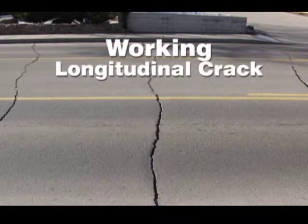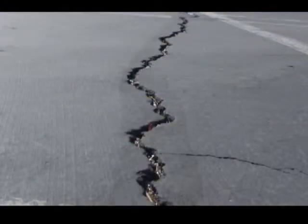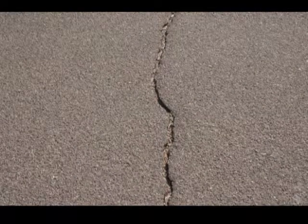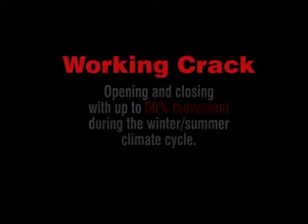The second type of crack is the working crack. The longitudinal crack is the most common type of moving crack, and we will focus on the proper type of crack repair for these types of cracks in this presentation. A working crack will move, meaning it will expand and contract, opening and closing with up to 50% movement during the winter and summer climate cycle.